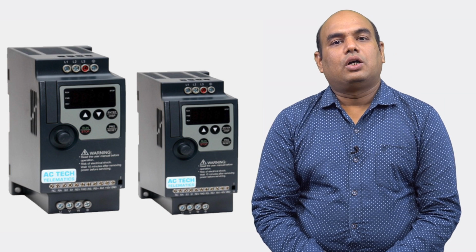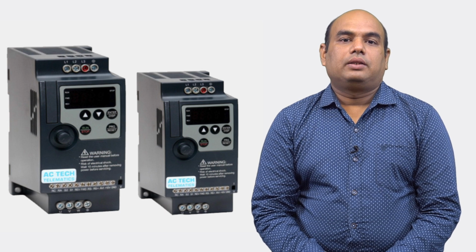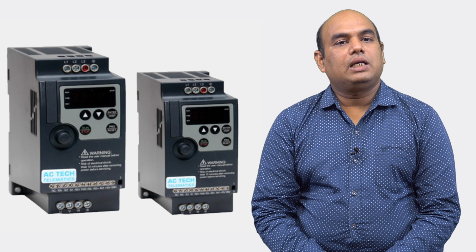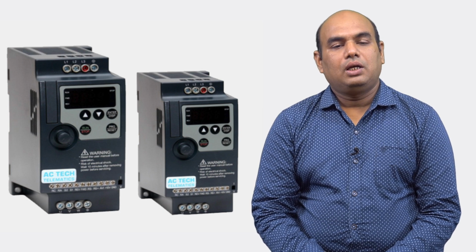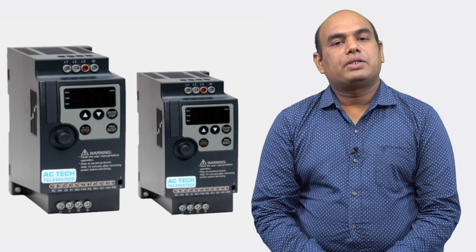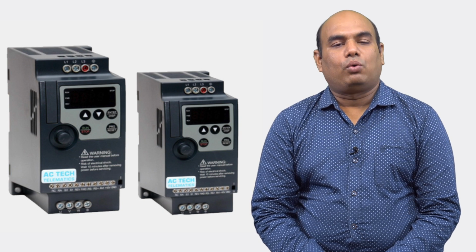The voltage control is possible in the inverter itself. The drive has regenerative braking capability. Full quadrant operation is obtained by reversing the phase sequence of the motor terminal voltage.